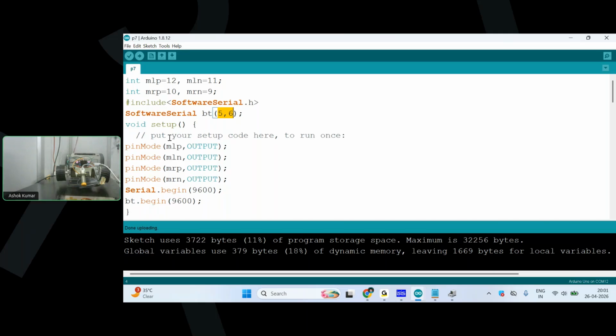You are transmitting the code from your PC to your Uno board using the cable. But actually you have engaged pin number 0 and 1 of your board. So the board understands this Bluetooth device as a programmable device, and it transmits the program to that Bluetooth. And actually Bluetooth is not a programmable device. So that time you face the error uploading the code.